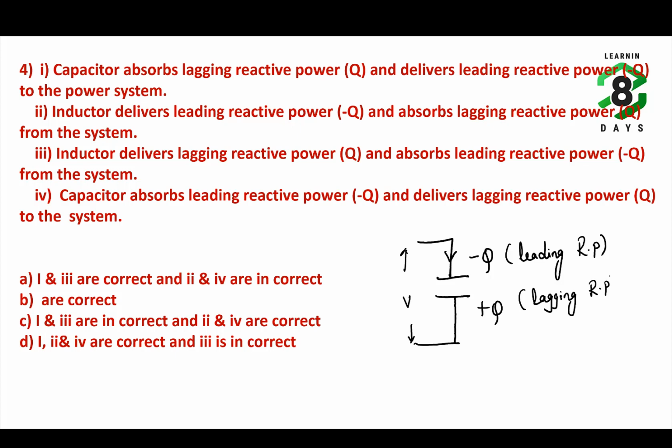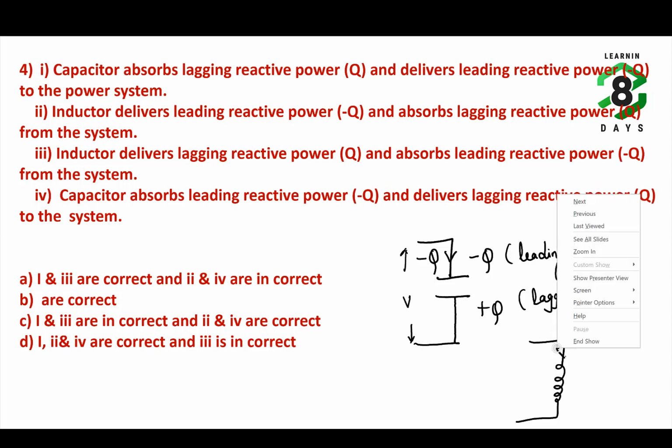So capacitor is an element that absorbs minus Q. Inductor is an element that, when you excite it with voltage, absorbs plus Q, that is, lagging reactive power.